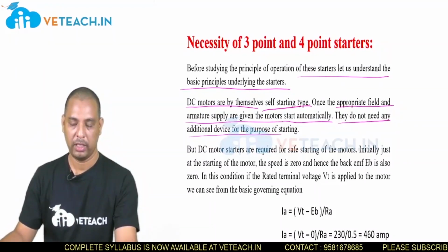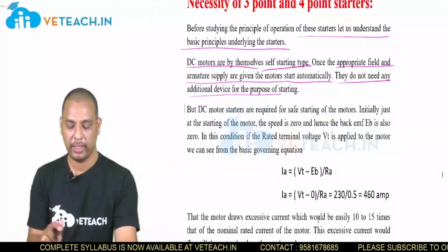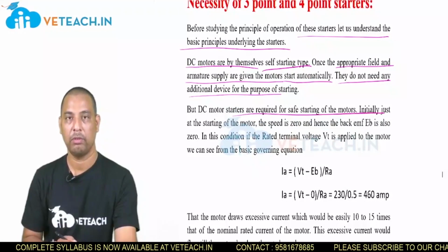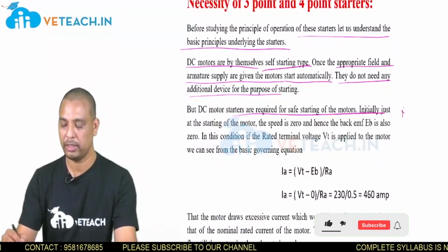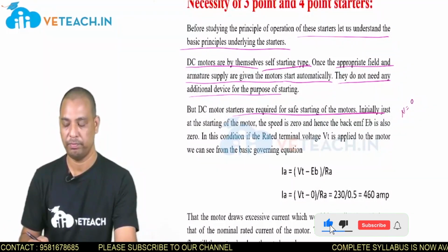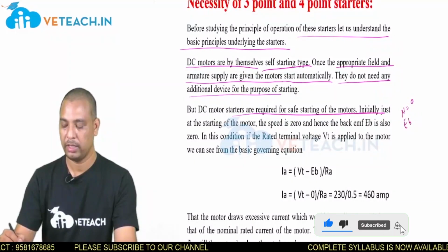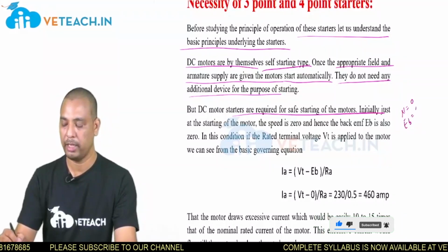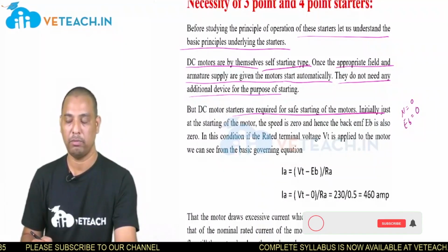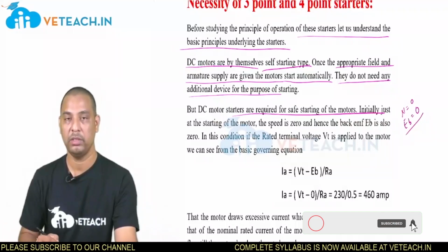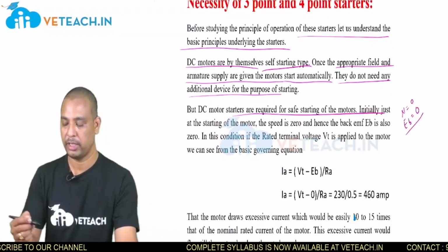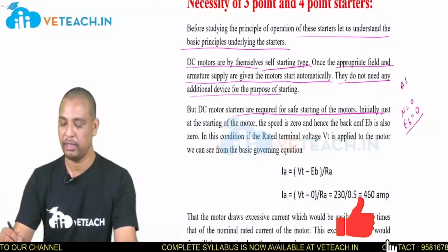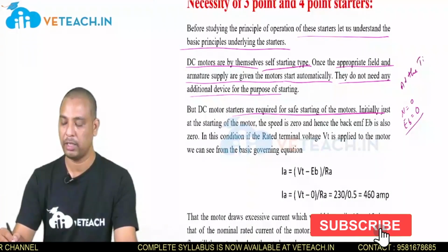But in the case of DC motors, at the time of starting, the speed is equal to 0, and when the speed is 0, the back EMF value of the DC motor also becomes 0. So that is the condition at the time of starting.